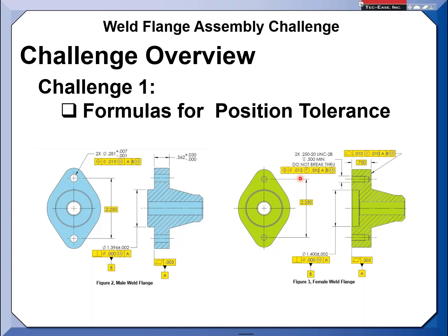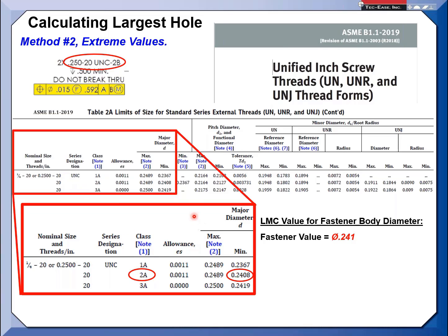And again, I personally like M's on threads. Not so much because I get the additional tolerance that threading could be out of position. If you look at the thread size, the bolt does have size variation for the major diameter, because it's a feature of size.